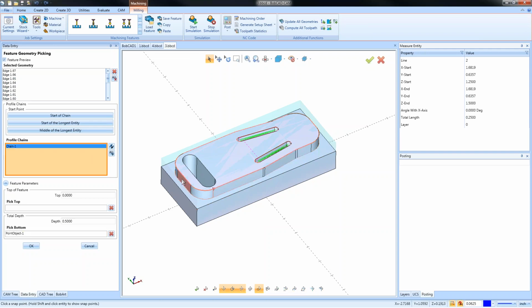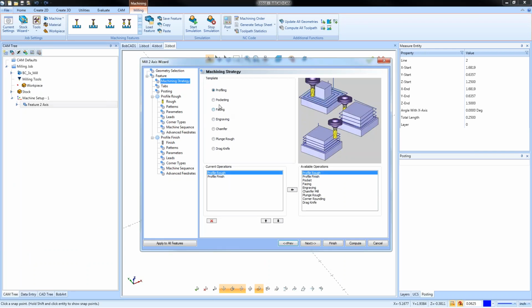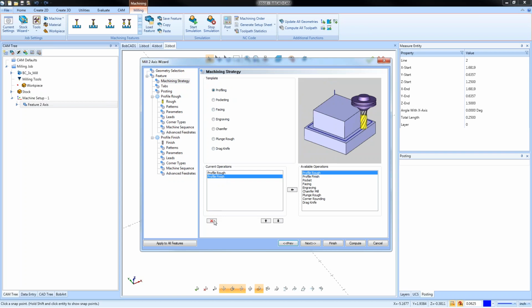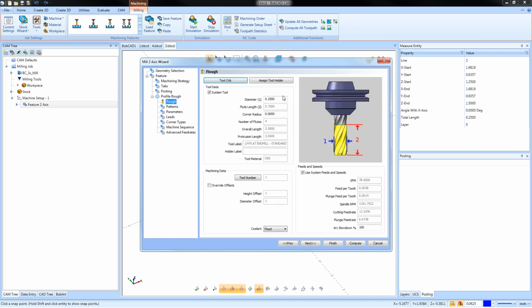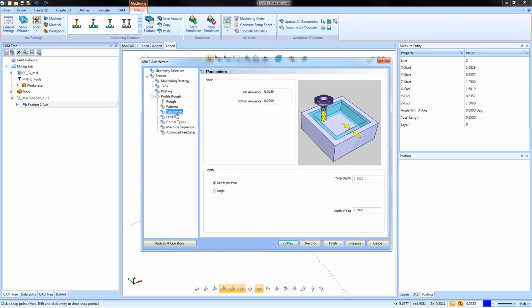All right, now again, we can pick how deep we're going to go. We have our chain start point. I'm just going to move that over here and set the direction. We may come in here with a larger kind of like feed mill or something along those lines. We'll just make this 750. Let's see if that's enough. We'll do contour ramping. We'll set our increment per pass.